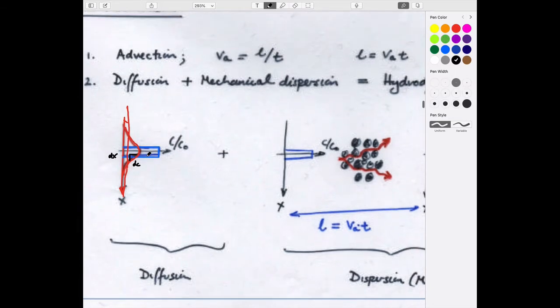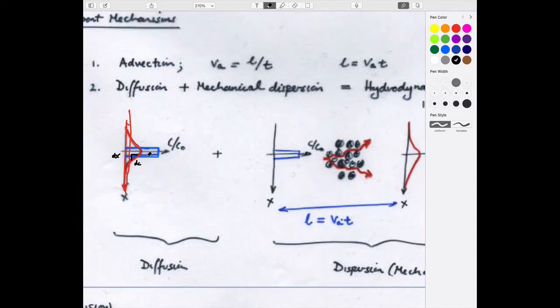But dispersion is physically a different process. And the idea is this. You start off upstream with this Manhattan skyline distribution, a single blob of the fluid. And as it goes downstream, it mixes, it goes down different tortuous paths. And if you look at it as it's downstream, then all of a sudden it's spread out. And so if you didn't know that you've moved from upstream to downstream, you wouldn't know that it's mechanical mixing. It just looks like the same process, which is diffusion.